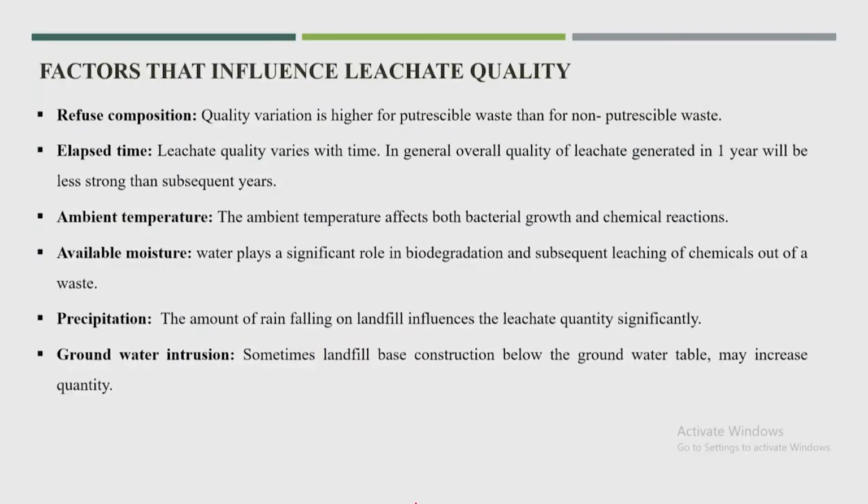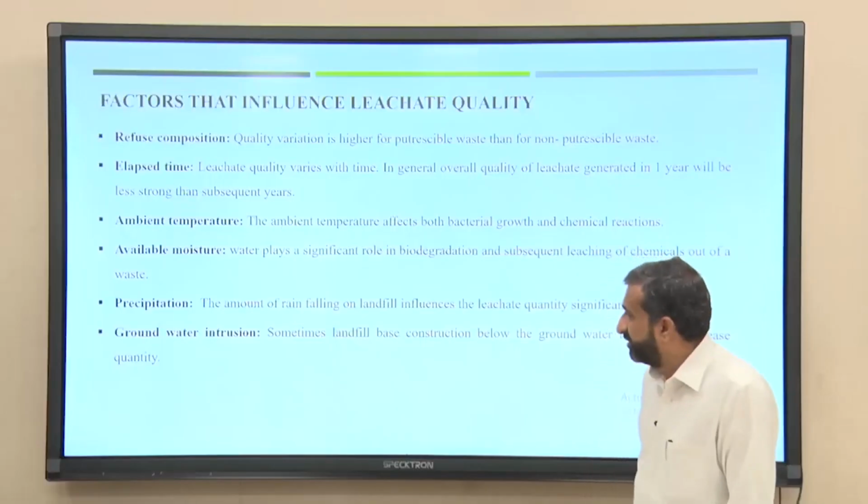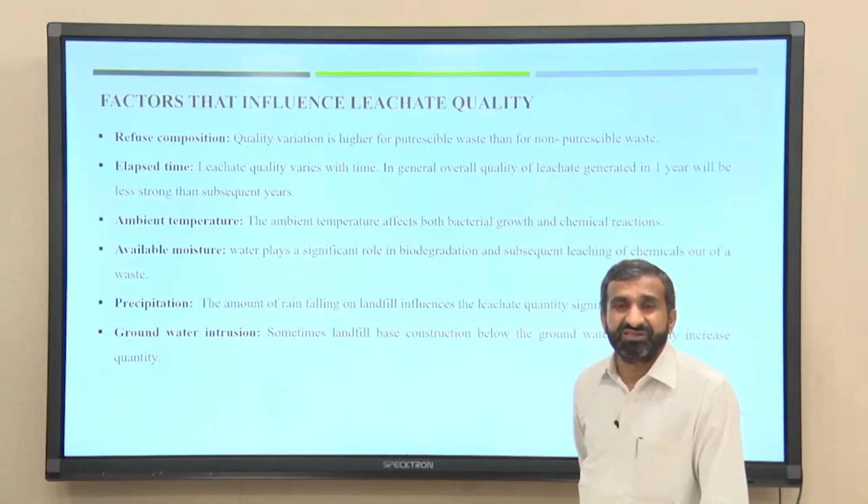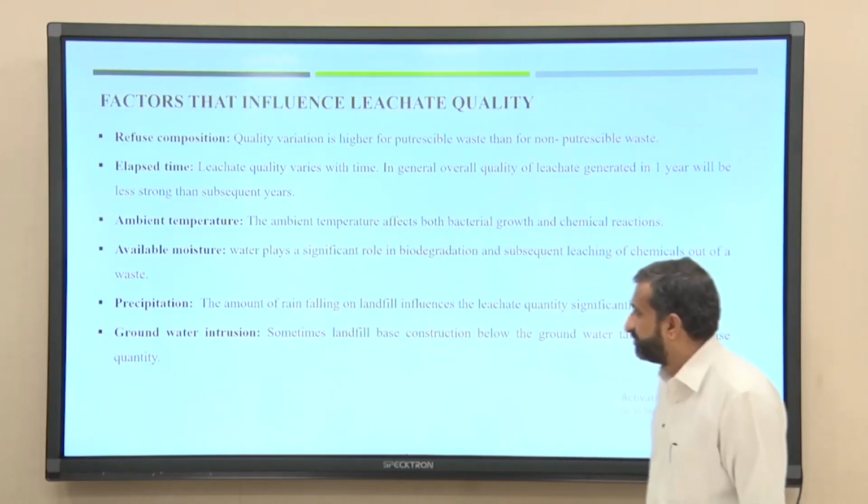Groundwater intrusion: sometimes landfill base construction below the groundwater table may increase the quantity. So, this is also one factor, groundwater intrusion could be possible. It depends on whether the groundwater is very close to the earth surface, or wherever you excavated the soil, then this intrusion could be possible. You can find this kind of intrusion very easily in the northeast part of India.